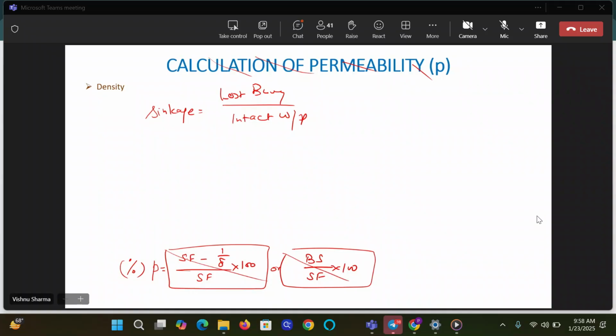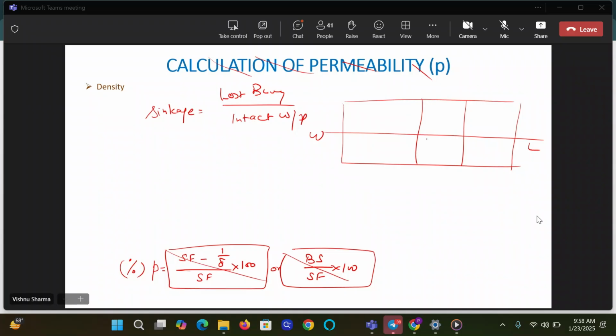When we were drawing the diagram, if some of you can recall, I said, is the water plane between WL and W1L1 identical in the bilged condition? Yes or no? Do you remember this? I am talking of the water plane area between WL and W1L1. I'm not talking from the keel. If this was WL, here was the cargo which was bilged, then what did I say? That, okay, this was the lost buoyancy, water rises here, this is W1L1.